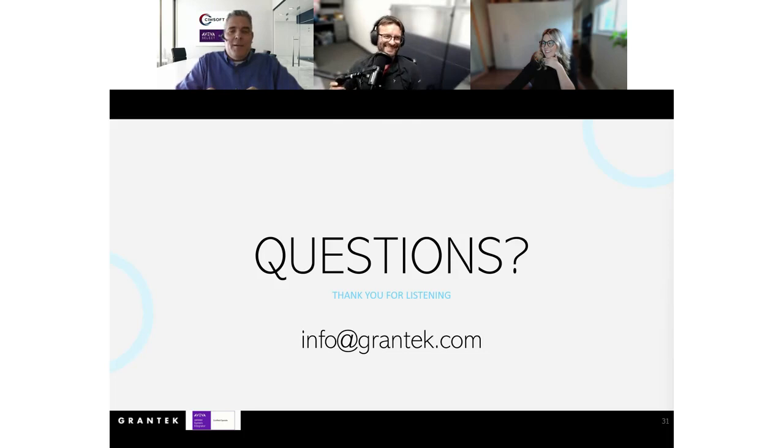Yeah, I can give that a shot. As soon as you have it in the PI Historian, AI can be applied to it. We have a product that's asset-based AI and we have process-based AI, so those are the two different ones. Asset-based AI is machine learning. A company like OPG, Ontario Power Generation here, would take the data from a PI server and feed it to what we call Advanced Analytics, formerly known as Prism. That looks at all these different parameters and has pattern recognition, so it predicts that a fan blade is going to fall off a motor.